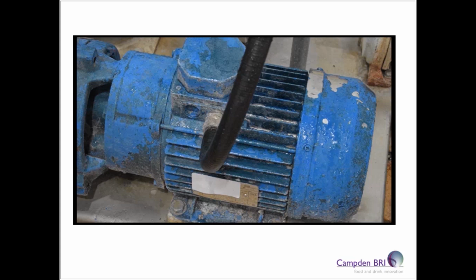Pumps are very, very common in the food industry, but actually maintaining them and cleaning around them is very important. The lubricants used must also be food grade as well. And often a common thing that happens in food factories is the pumps are placed right underneath the tanks, meaning that they're very difficult to get at. And this is a good example here. You can see on the right-hand casing where there's moisture and water, and there's also paint flaked off. So not a very good example, but typical of what can happen in a food factory. Nearly 2,000 non-conformities have been raised against this clause.